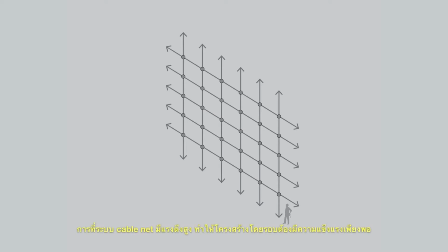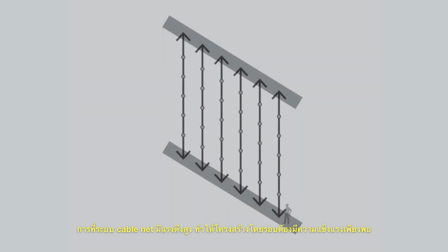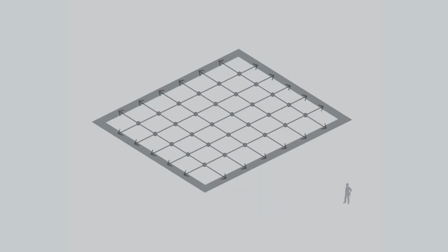The fact that the cable net system requires high pre-stress force impacts the boundary structure significantly. The boundary structure has to be sufficient to take the high pre-tension force. It's even more challenging with a system that is not vertically glazed like skylight or canopies.